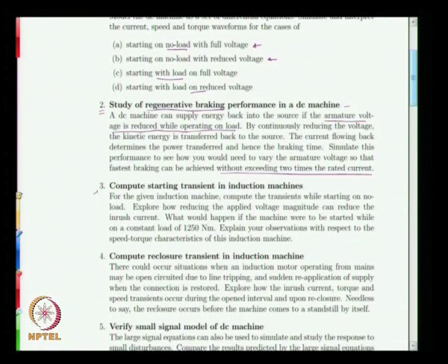The next assignment is on induction machines. How to determine what will happen to the induction machine when you start. Now for starting of induction machines, I am sure you would have heard of star delta starters that are used. Why are star delta starters used, and how does the machine behave even when those are used? One can study in this assignment how much inrush current the induction machine takes, if you can model the grid also appropriately. After all, the induction machine gets its 3-phase supply from your electrical utility supply.